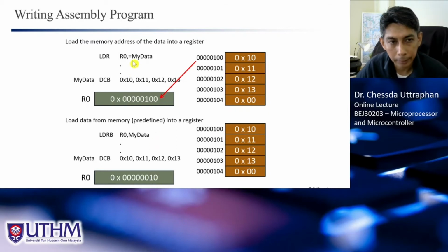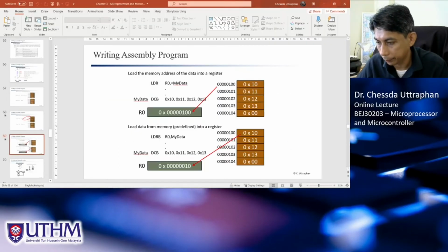And again, this is not an instruction set instruction. Actually, this is an assembler directive. When you write it in Keil, it is actually converted to an equivalent instruction. So for example, let's try to write this in Keil uVision and see what happens when we do that.